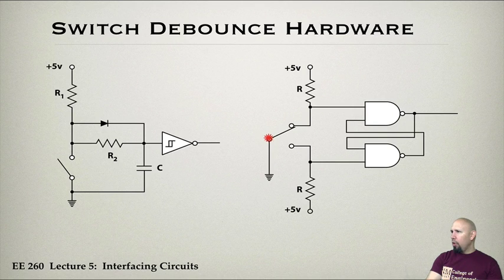This is what's called a single pole, single throw switch. So this is the pole, the thing that it's attached to, and it touches one contact over here. It can only touch one contact. So single pole, single throw. This is a single pole, double throw. In other words, this switch contact can be in either of two positions. In the first case, it is either on the contactor or it's not on that contactor. In this case, it can be either on this contactor or on that contactor. So it's a different kind of switch.